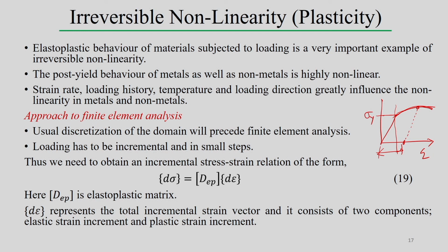Now, if we do only the thermal analysis, depending upon the thermal cycle or thermal load, we can do the analysis and get the output as a temperature distribution in the discretized domain. But in stress analysis, because of the nonlinear nature beyond the yield point, in that particular zone it is better to follow an incremental mode of analysis. It means that in this nonlinear zone we consider small increments of the strain.